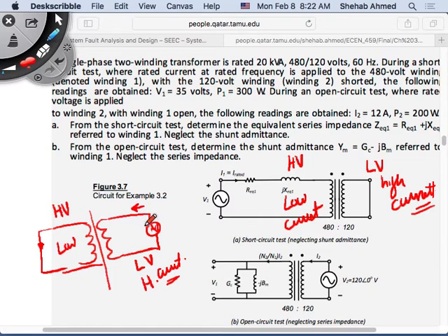So instead of getting a power supply with a high value of current, it's cheaper to conduct this test with a power supply with a low rated value of current, right? So you would conduct the short circuit test from the primary side for that purpose. But does it matter? No, it does not matter really. You can do it this side or that side, right? It does not really matter at the end of the day. But just from an economical perspective, people would do the short circuit test this way.